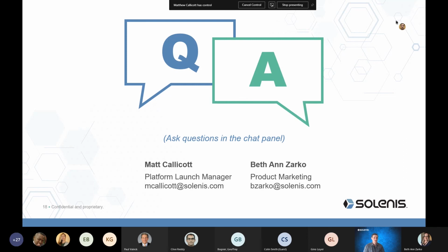The biggest need, because it is a data-driven solution, is a connection to that live historian. So, if the customer does not have significant historic data, and when I say significant, we typically look for 6 months to a year. We've been able to do less, so I'm not saying exclude them if they have less than that, but it becomes more of a case-by-case basis to understand what the capabilities are of the historian that they currently have. We have to have the ability to get that information in a 15-second, 30-second feedback so that we can be providing this real-time prediction.